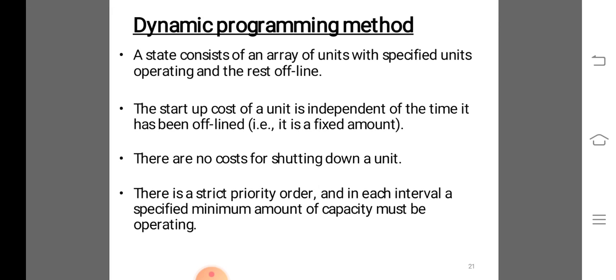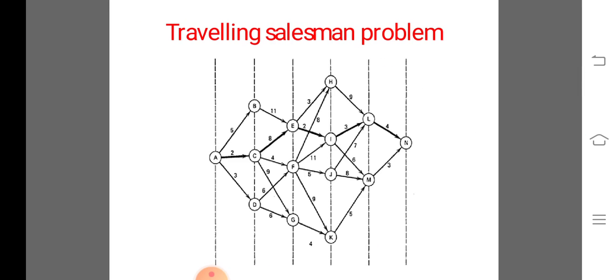A forward dynamic programming algorithm is shown by the flowchart. The recursive algorithm computes the minimum cost in hour K with combination I. Then this is like the traveling salesman problem. This problem will take the combinations in the forward dynamic programming approach.